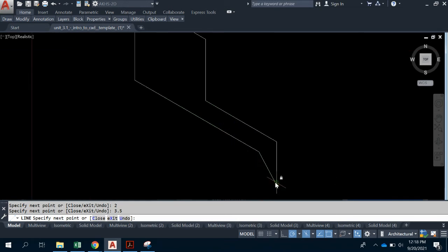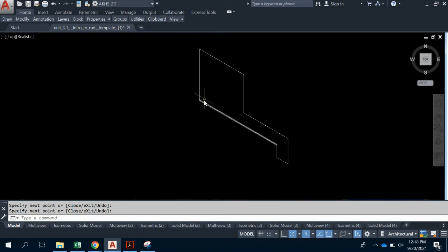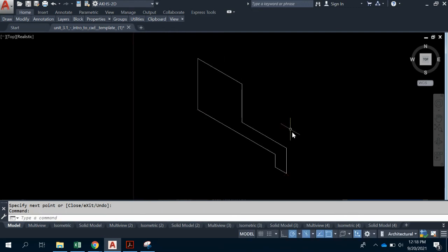And then sometimes we even think we typed it in wrong, and it's possible that you just typed it incorrectly, and you're reading it correctly, you just typed it wrong. So just be careful and pay close attention to that. So once you get this front profile, it has a constant depth throughout the whole thing, or uniform depth throughout the whole thing, which is 2. So we can just go line, and we can go from each of the corners up and to the right 2.